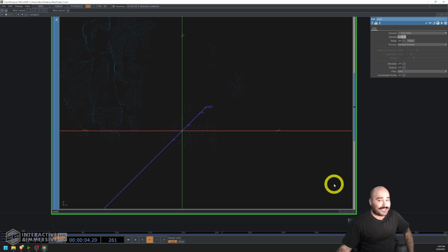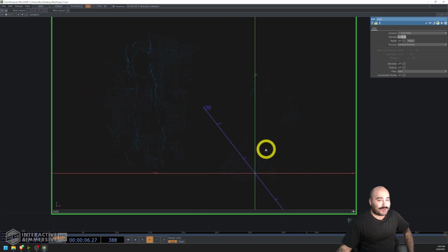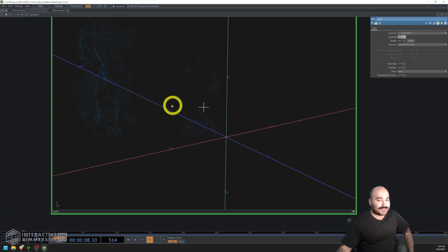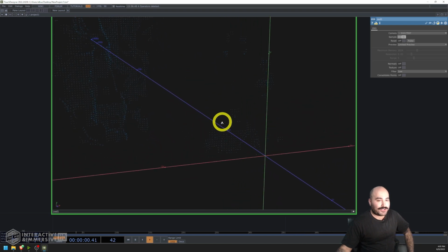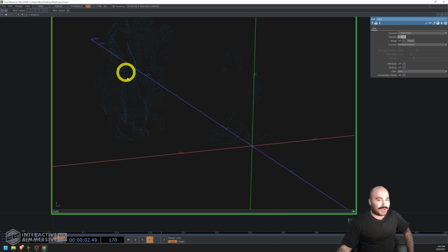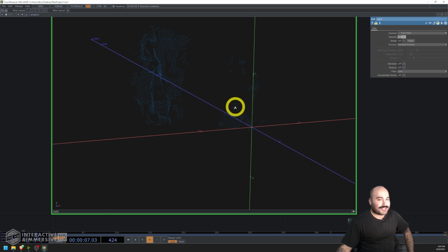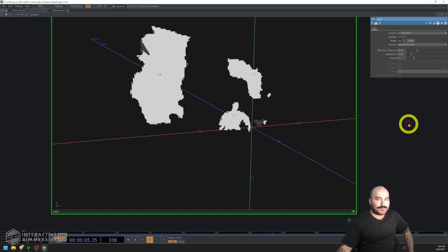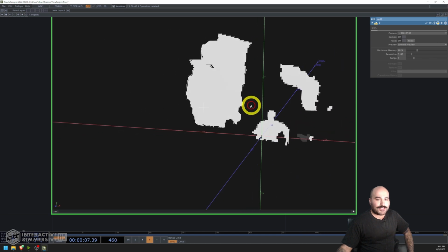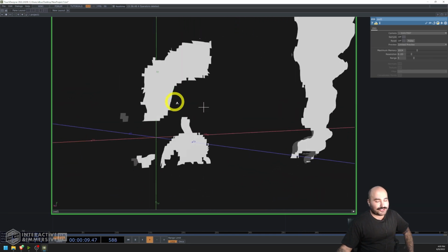it's starting to fill in inside of the SOP the different points that it's finding and scanning. So you can see I'm up in the front here, and these are the walls behind me. Once you're done your scan, which I usually say if it's a static scan, give it maybe 5 or 10 seconds. It does go through and fill in a lot of points. Once you're done, you can go ahead and hit sample. It's going to finish the process and report back to us a mesh.